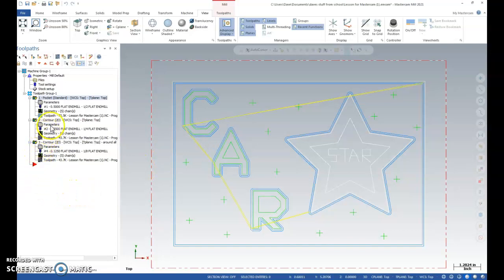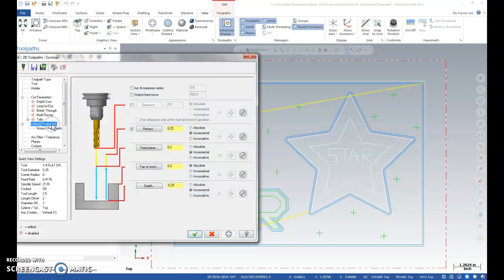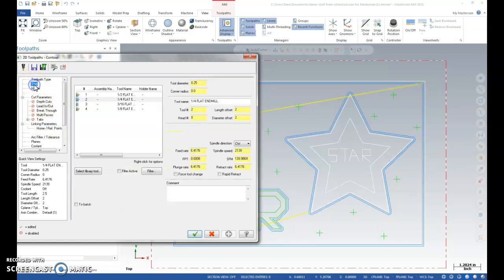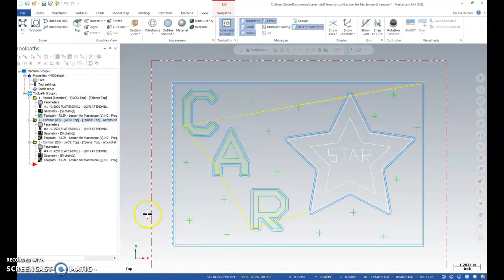I also know I made the mistake here of the wrong speed, so I'm going to fix that now before it's too late. So parameters. And if you'll notice up here, when I go to the word tool, the quarter-inch is picked. There it is. It's tool number 2, but I forgot to make this 59. And again, that's important because later we want to be able to quickly change to the right speeds for wood after we do our foam mock-up. All right, and here I would write, blah, blah, blah. So, okay, great, checkbox. You'll notice that is done and looking good.